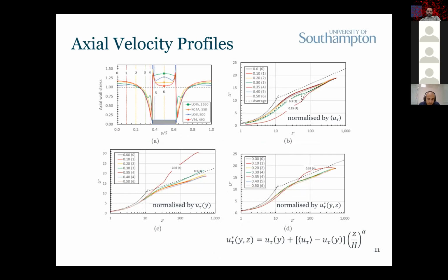The next one is axial velocity profiles in different spanwise positions. So we took 7 different positions, from 0, 1, 2 to 6 here, which are different spanwise positions, and these are the axial velocity profiles. Normalized, the first one, bottom left corner, is the curves of axial velocity normalized by the local U tau. Local U tau means the U tau calculated at each spanwise location separately.